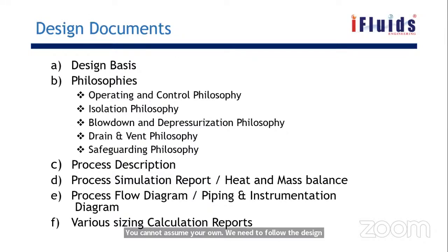Design basis will be prepared with the help of different standards, like API standards. And the design basis is applicable for all disciplines: process, piping, instrument. So all the teams need to follow the design basis. And then the philosophies will be generated at the initial stage of the project, which we need to work with. Say the operating and control philosophy, which we talked about: how the temperature needs to be controlled, how the operation needs to be done. All those things will be given in the operating and control philosophy.